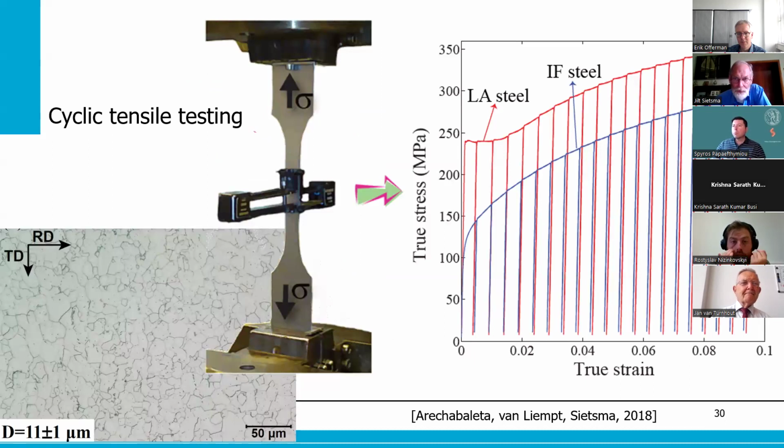So we did this. And that's one thing I have to say. These are very careful experiments with 2 extensometers, and that's because in general, a tensile test, or machinery, has been optimized to study the plastic behavior. And we want to study the elastic pre-yield behavior, the elastic and inelastic behavior. So very small strains, so we have to be very careful with straight samples, perfect alignment, etc., because those are things that are not so important when you study plastic deformation, but are very important, of course, if you study the very small scale of the pre-yield behavior.